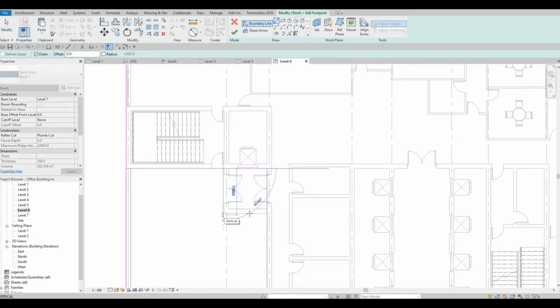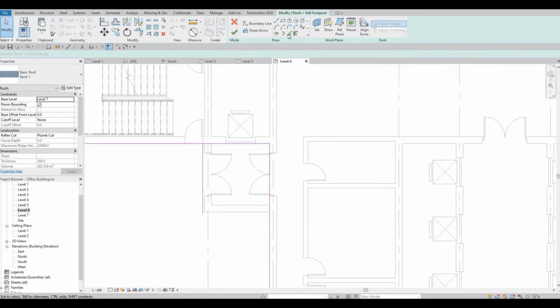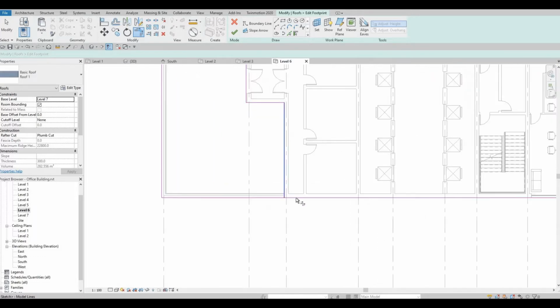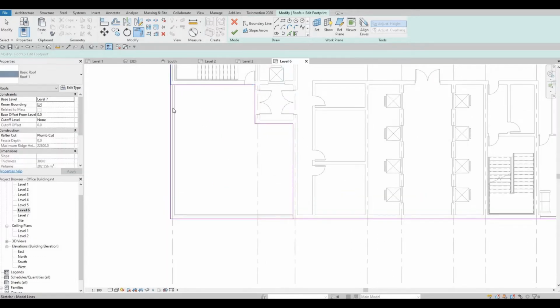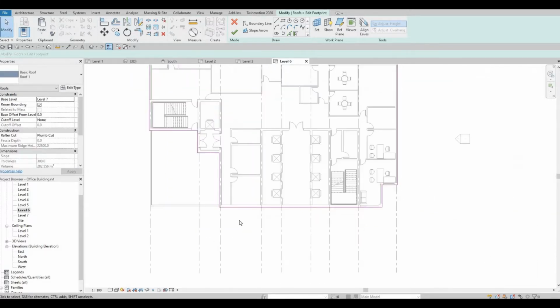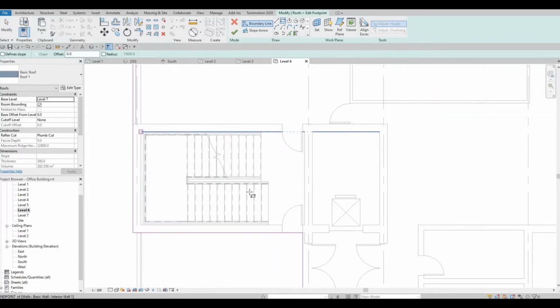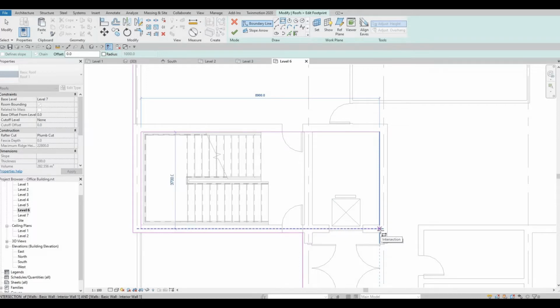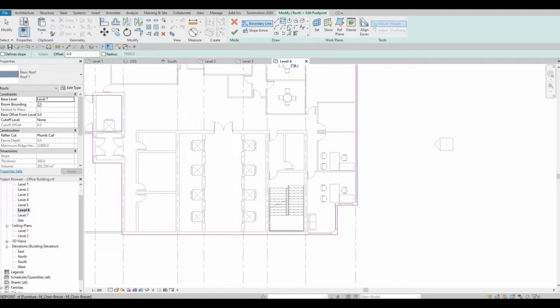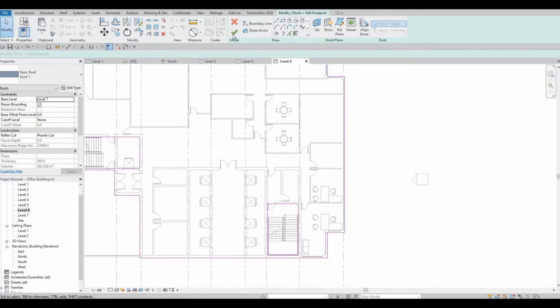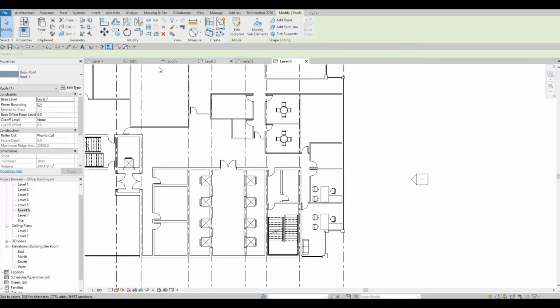and I'm gonna use this. I'm gonna trim this, trim that, trim that, and trim this area. And then after that, let's open this. So I open that and this area as well. So click finish and let's look at it at 3D.